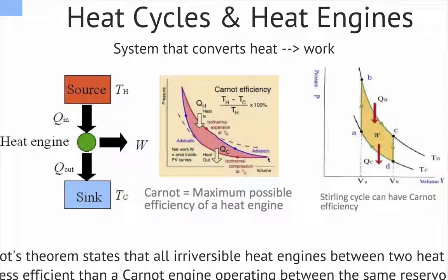Now, you can compress that gas, let's say, by isothermal compression. It doesn't need to be isothermal, it's just an example here, at, let's say, Tc, which then reduces the volume and increases the pressure. But of course, when you compress it, the heat comes out. So that compressor, of course, generates heat, as you remember from the example of the refrigerator. Then there's an adiabatic compression, okay, which is basically energy conserving compression, and it comes back to its initial state.